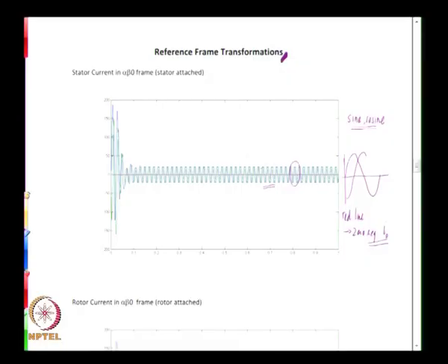This is again true also because even if you were to supply an unbalanced excitation, as long as the machine is star connected, even if a 0 sequence component were to exist in the applied voltage, 0 sequence flow of current cannot be there. Star connected plus isolated neutral. In the case of induction machines, neutral is invariably isolated.